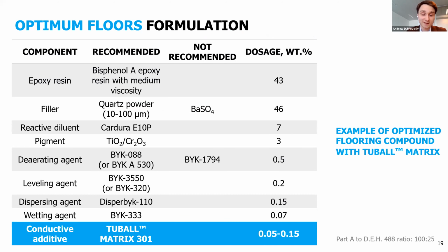Today we have a great experience in dissipative and electrically conductive flooring. We are able to provide you with some specific technical recommendations, with some specific technical tips from our side related to the optimization process of the formulation. For example, we have noticed that some types of fillers are working a bit better with single wall carbon nanotubes. For example, quartz powder is preferred to barium sulfate.